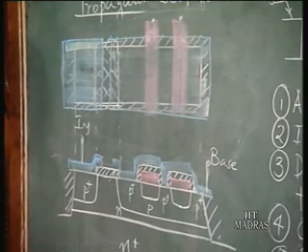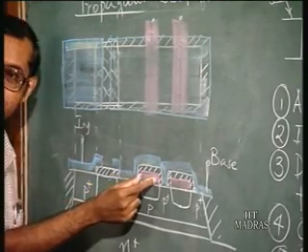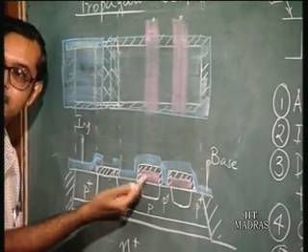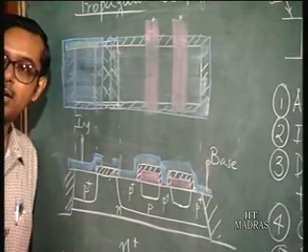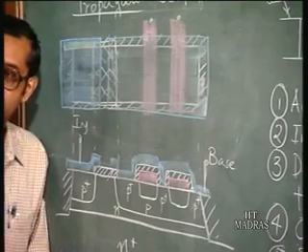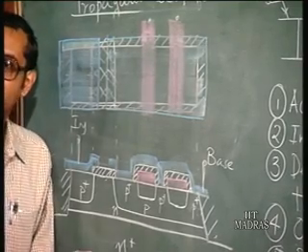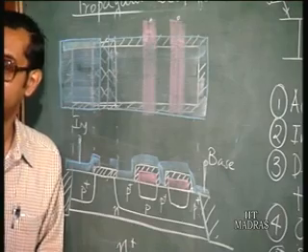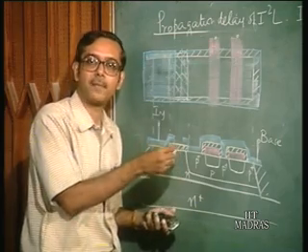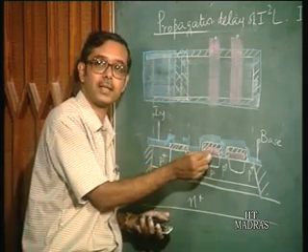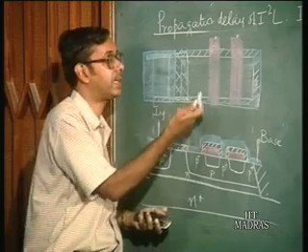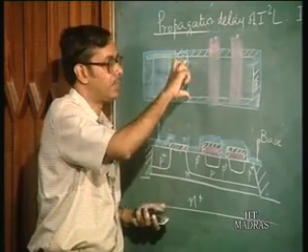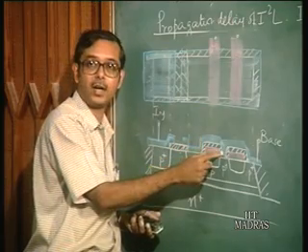Now see what you have achieved. This is the collector. This polysilicon itself is acting as the contact, much in the same way as in a MOSFET technology where you have poly gates, with the polysilicon acting as the gate material as well as for metal lines. So this is the collector contact taken through the polysilicon. It goes this way, and this is the base contact.